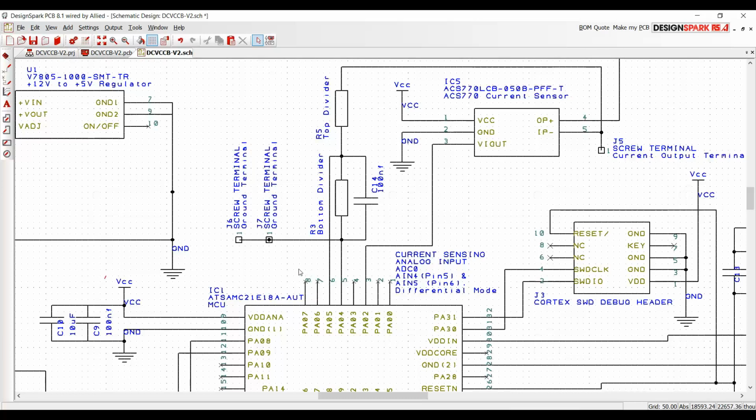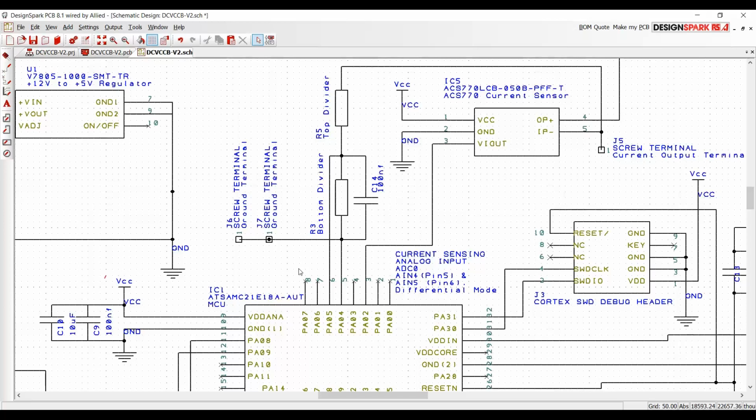And then the last possibility could be just simply to switch the voltage and current inputs from what I'm trying to do. I put voltage on ADC0 in differential mode because it seems to be more amenable to the lower numbered pins and doing it differentially. Put current over on ADC1 because it has only 2 input pins and seems to really want to reference it against the analog ground. I'm going to go have a strong drink while I upload this.